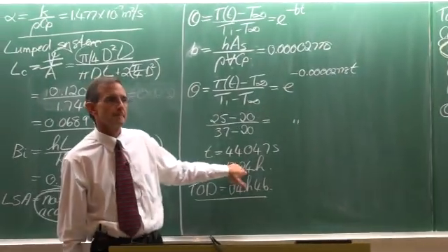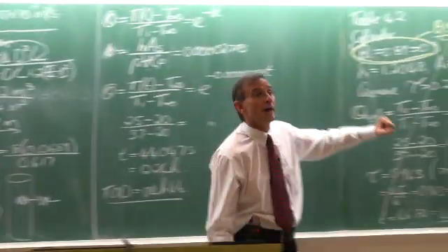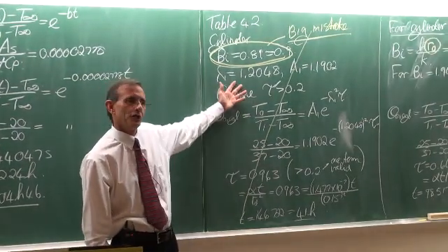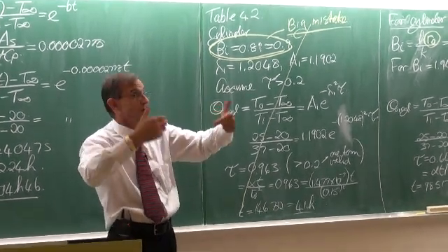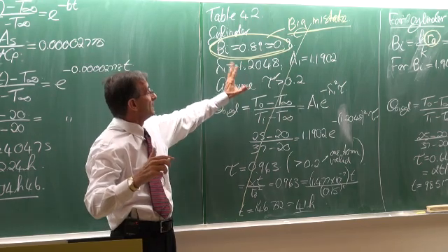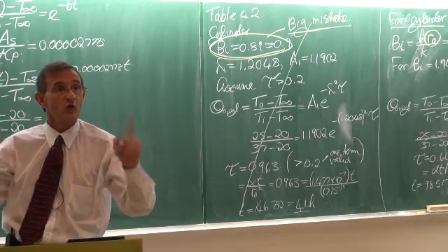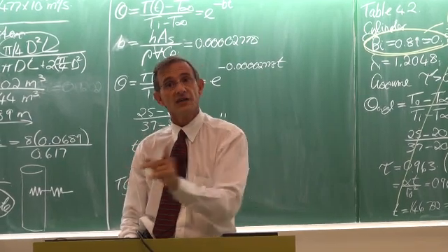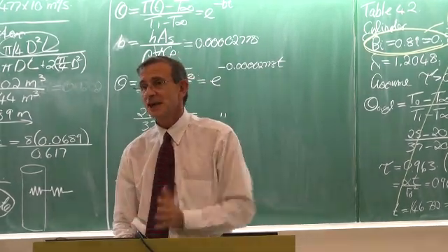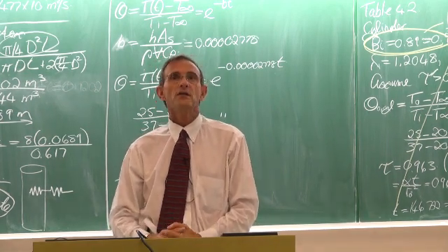Okay. The lump system approach, 12 hours. The more accurate one, 27 hours. And the trap. Don't fall into it. I told you there's a very important paragraph that confuses many students. I've made it very clear to you. This calculation of the characteristic length you only use for the lump system, and then you calculate that Biot number. For all the others, you do it differently, so don't do it the same. Any questions, ladies and gentlemen? Nothing. Thank you very much.